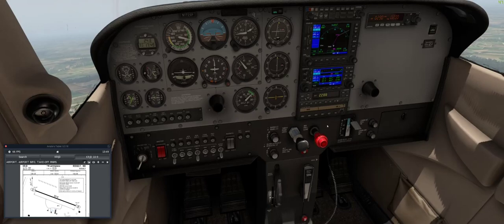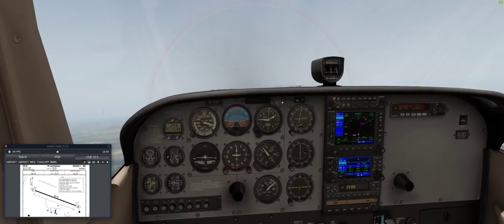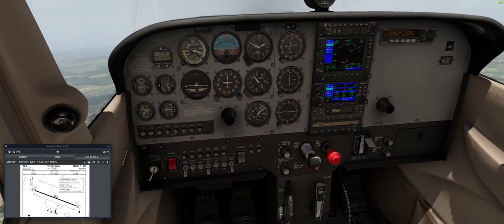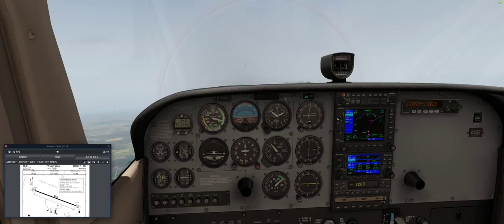a less climb angle, which I'm going to do because it continues to drop. So I'm going to go down to 600 feet per minute and watch this change, and watch our airspeed will start to climb back up again.